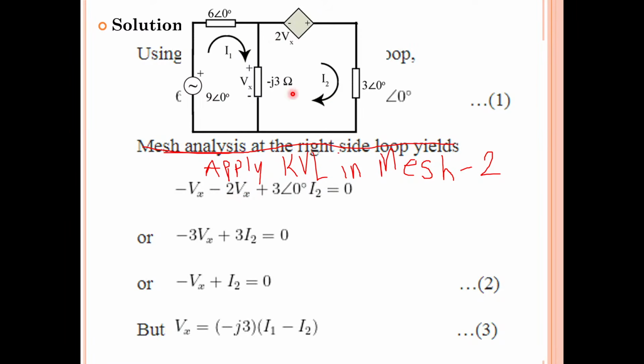See, in these two, just observe this loop current. Current I2 is in the clockwise direction. So current is flowing downward in this element, and current is flowing upward in this element, so these two are in the same direction. Therefore, these two elements' current directions are the same, and this element's current direction is different. So if I consider these two as positive, this should be negative. If I consider these two as negative, this should be positive.